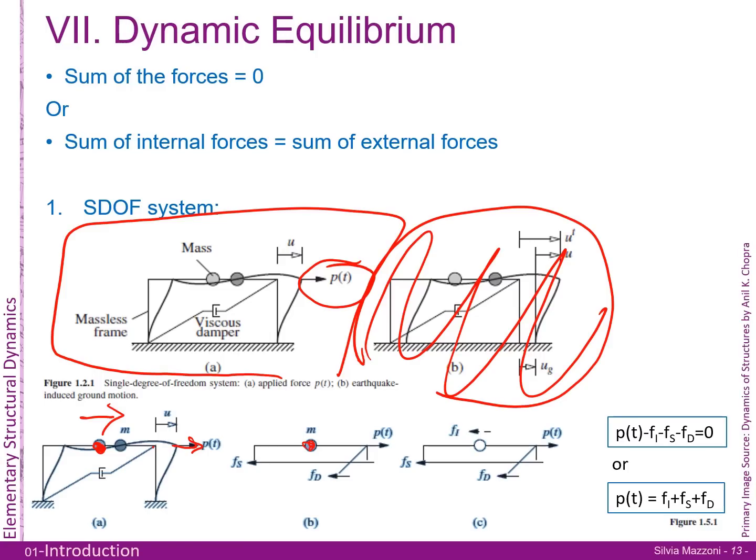We have this mass, which is an internal force, going to be our inertial force that's going to go to the left. We have our resisting force that's going to be a shear force in this direction, due to these forces here, the force that is required to deform the columns and the beams too, okay? That's when things get interesting and complicated with structural analysis. And you also have a damping force that acts in the direction of the damper.